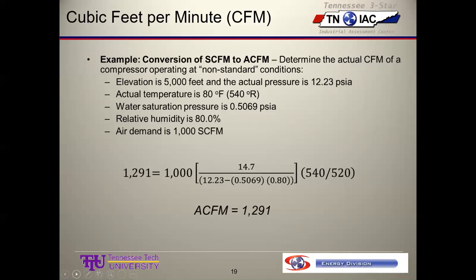And that's what the compressor operating in that room needs to satisfy that demand, because equipment that consumes compressed air has a rating. Typically it's 100 psi pressure and standard conditions. Well, you're operating in Denver, you're not operating at standard conditions, and so you would need almost 1300 CFM for all this equipment that was rated to consume 1,000 CFM standard.